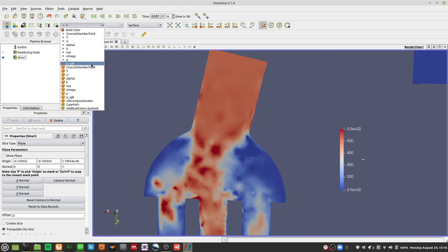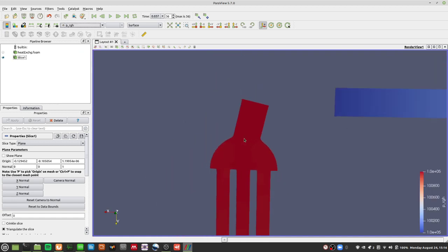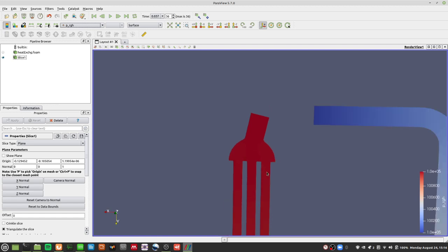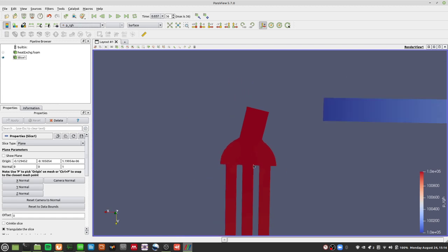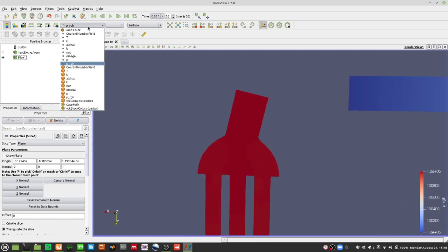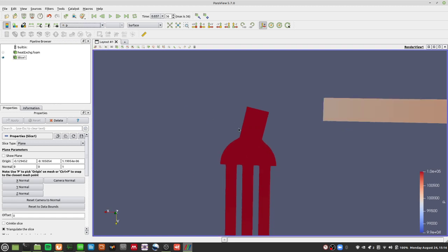So let's take a look at Prgh. Now Prgh tells a different story. Can you see that the pressure here, we don't really have any localized spots of high pressure? So that's something amiss. Normally when you compress air, the temperature will increase, but what we are seeing here is that all these parts are labeled red. This is Prgh, the pressure without the hydrostatic component.